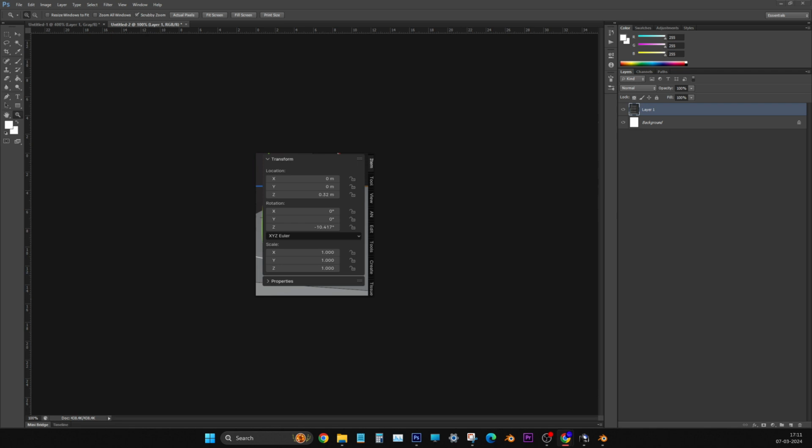Okay, then actually there is a little overlap, no? So I think 9 5, 6 9 5 will do, I think. Just try. Yeah, this is okay. Enough. Right. Now you select the object mesh staircase. Now you can increase the count like 78 or something.